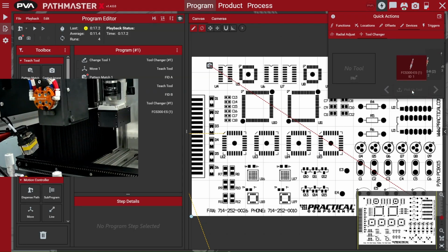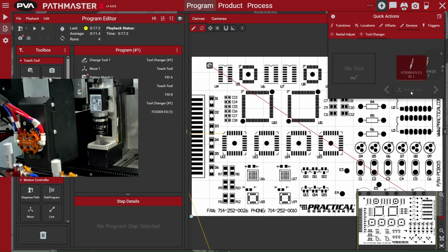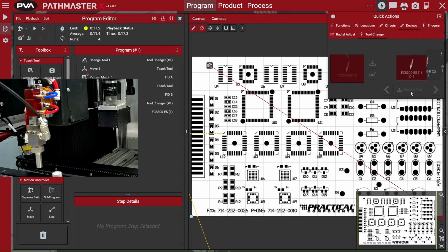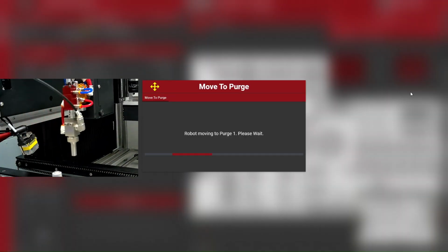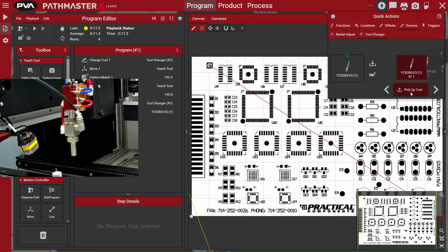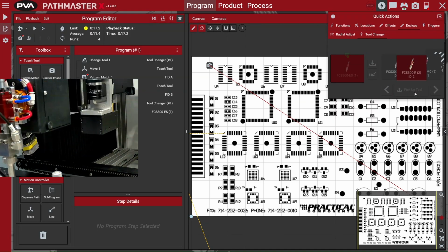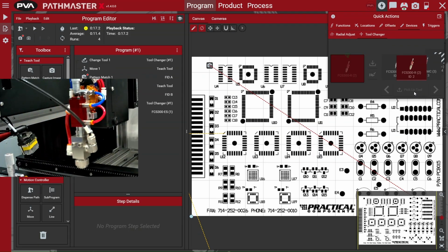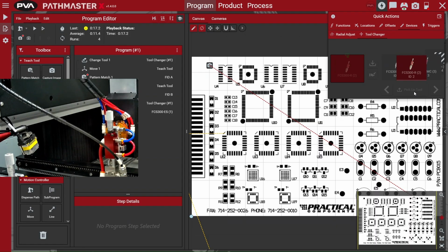The Tool Changer menu also has a control for automatic tool retrieval. Select any tool and press the Pick Up Tool button. When a tool is picked up, the post-pickup trigger will execute. Picking up a tool when one is already held causes the pre-drop trigger to execute and the held tool to be dropped off. The desired tool is then picked up, and the post-pickup trigger executes.